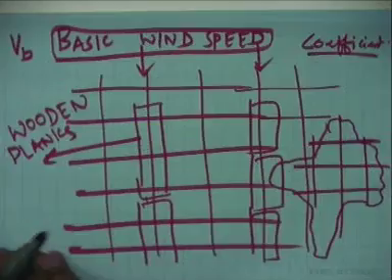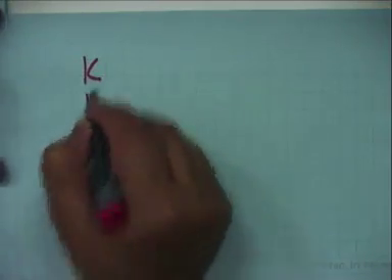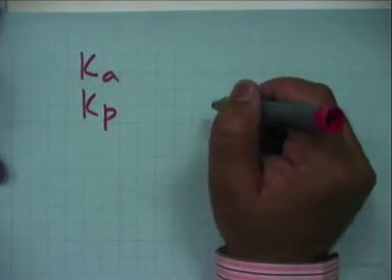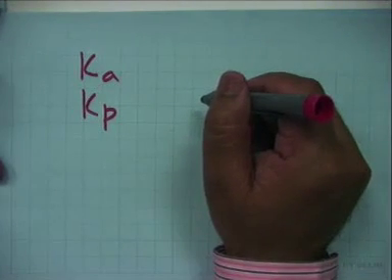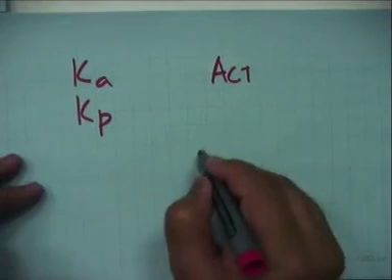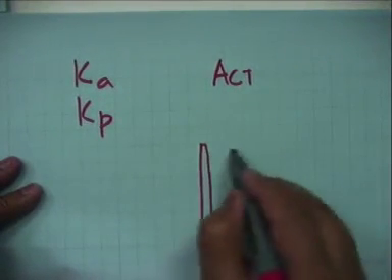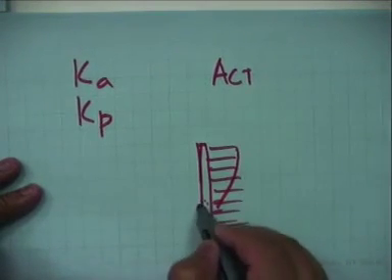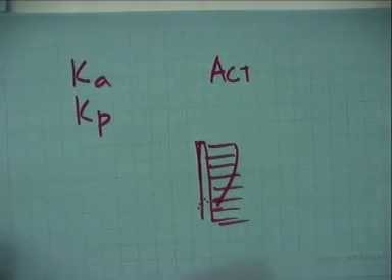Similarly, if your formwork is against some earth fill, then it will again exert lateral pressure on the formwork surface. So, this you must be knowing, the active earth pressure, the passive earth pressure in soil geotechnical engineering. That you know. So, the same thing you will have to apply. Suppose your formwork is against some earth fill. Suppose this is the earth fill and you have a formwork. So, this will exert some pressure here also. So, how to take care of that? All those things come here.